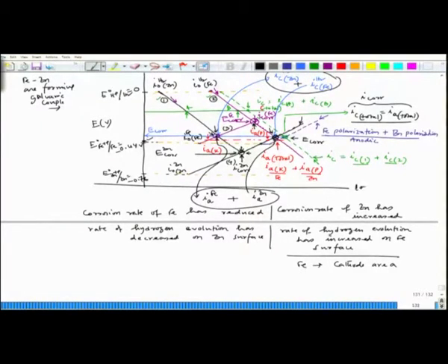Remember, this is in log I scale, which means that the decrease is quite a lot, because it could be of the order of 10 to the power 2 to 3. So, iron becomes the cathode, and since the rate of hydrogen evolution on the zinc surface has decreased, that means the cathodic reaction is less on the zinc surface.